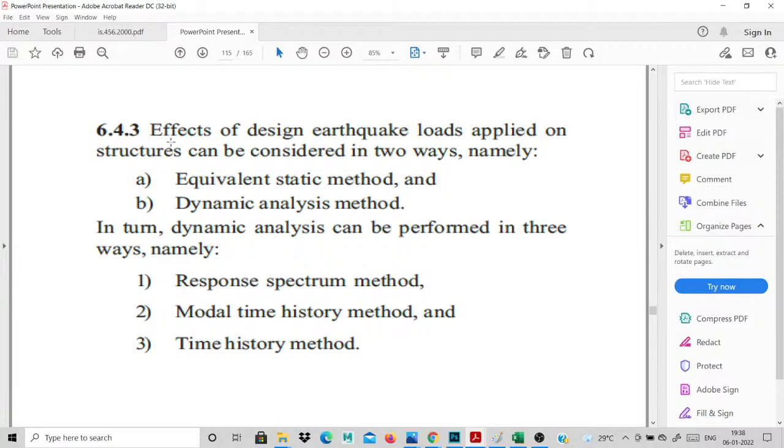The earthquake force, how much force will be acting on your building, is called lateral force, and base shear. Once you have calculated the base shear values, you choose how to resist it for your buildings: retrofitting, seismic dampers, viscous dampers.